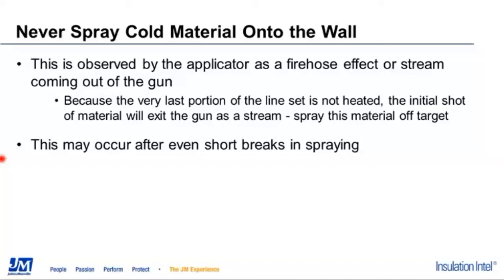So when you first pull the trigger, you're going to get what we call a fluid fire hose effect, or a pencil stream that runs out the front, where this material's not thin, it's not heated up, so we don't get good mix out of it. We cannot be putting that inside of the substrate or cavities or on somebody's wall. We need to make sure that we've got a piece of plastic, a cardboard box, a garbage sack, whatever it is that you've got with you in the spray environment so that you can spray off target.